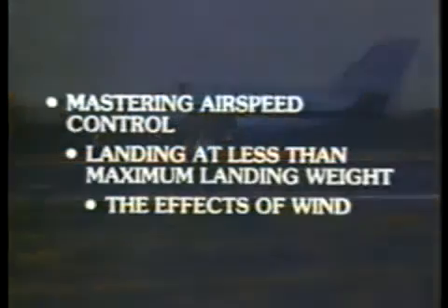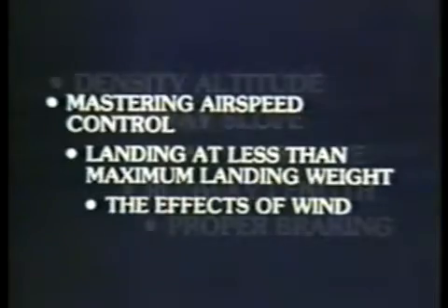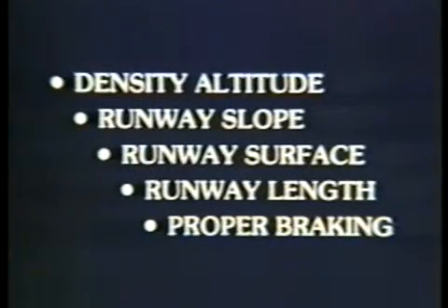To review, we talked about mastering airspeed control, landing at less than max landing weight, and the effects of wind on the landing rollout. We also looked at density altitude, runway slope, surface, and length, and talked about proper braking techniques.